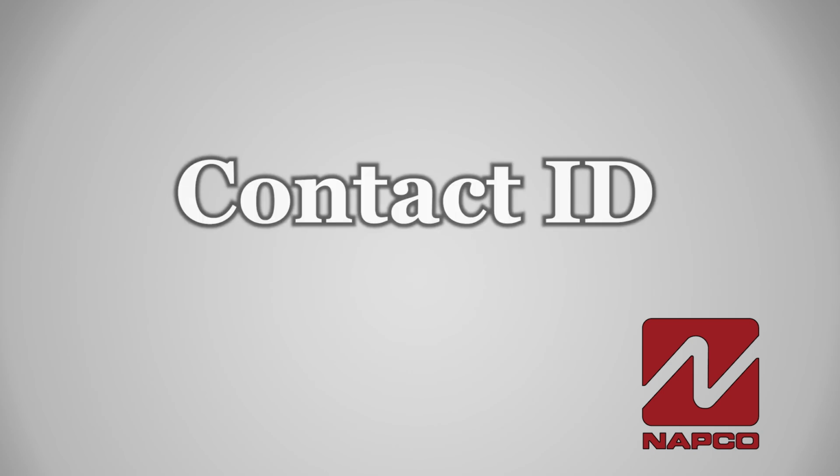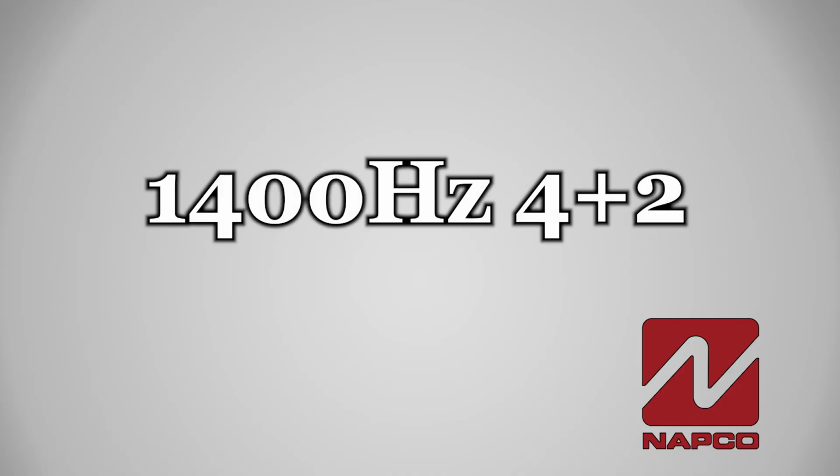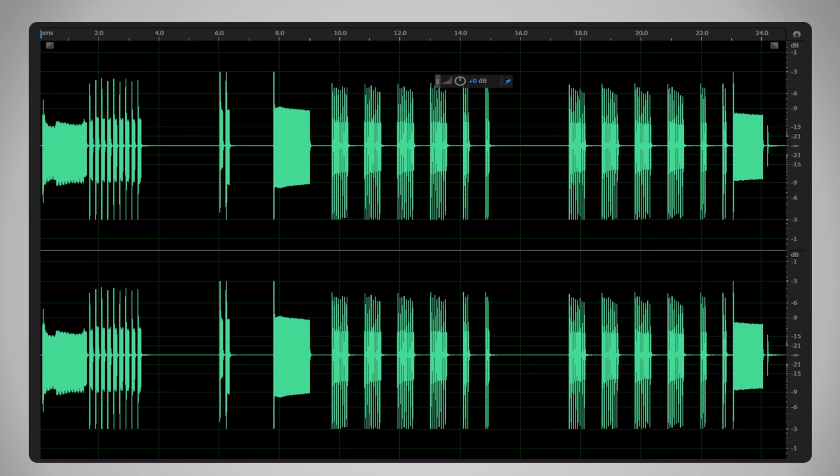When you pick up and dial out to the radio, it will rotate through 3 handshakes. When your panel hears the handshake it is waiting for, it will respond. The 3 handshakes by default and in order are contact ID, 2300 Hz 4x2, and 1400 Hz 4x2. This is what a successful 2300 Hz 4x2 transmission sounds like.